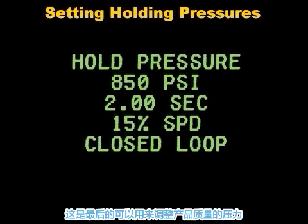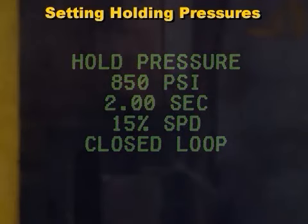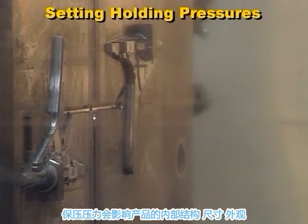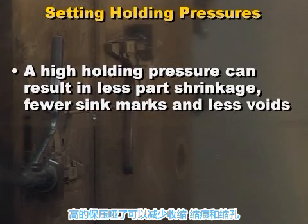These holding pressures are the final pressure adjustment the molder can make to change part properties. The amount of holding pressure affects the internal part structure, part appearance, and the final part dimensions. A high pressure puts more plastic in the cavity and results in less part shrinkage, fewer sink marks, and less voids.